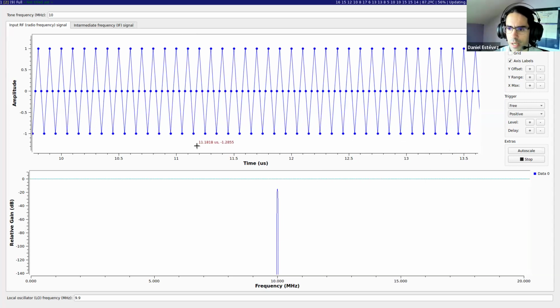Maybe you have seen a voltmeter, so that measures the voltage of a signal. An ADC is the same as a voltmeter, but it operates very fast, and it periodically samples the signal. It takes a voltage measurement here, etc. And that's basically how we get electrical signals which are continuous in time into the computer, which can only handle discrete numbers, if that makes sense.